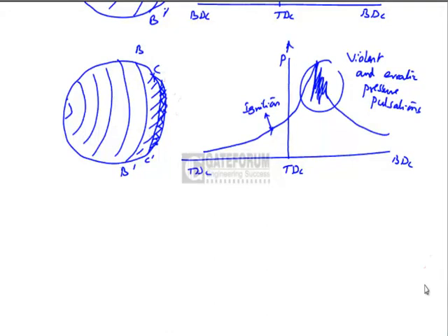This particular charge would auto-ignite due to self-ignition, the temperature reaching the self-ignition temperature and the ignition delay of this portion of the charge being complete.